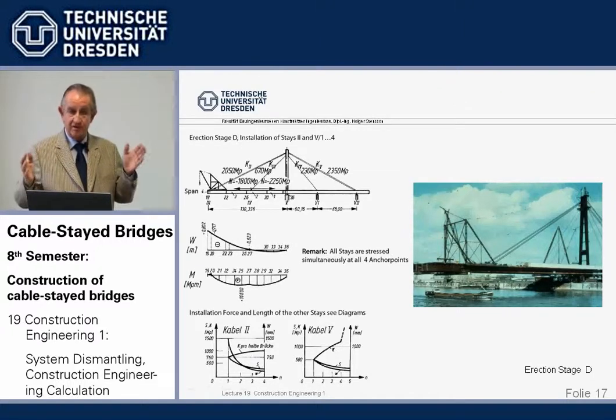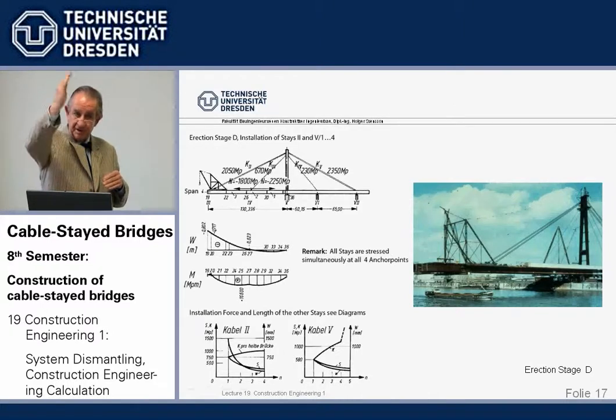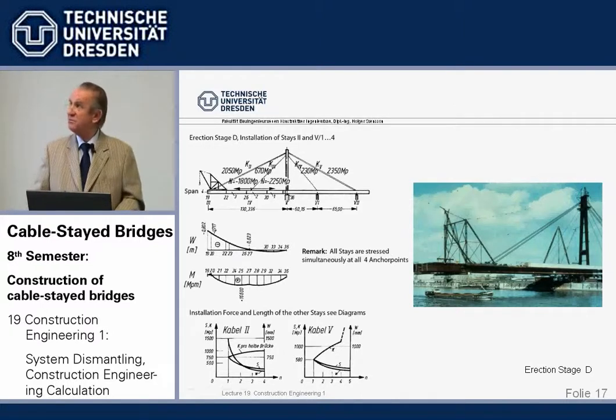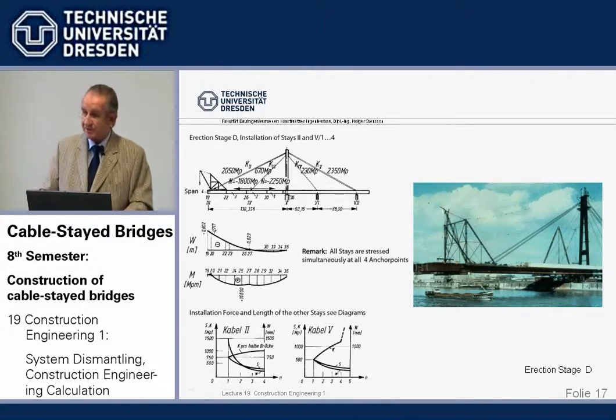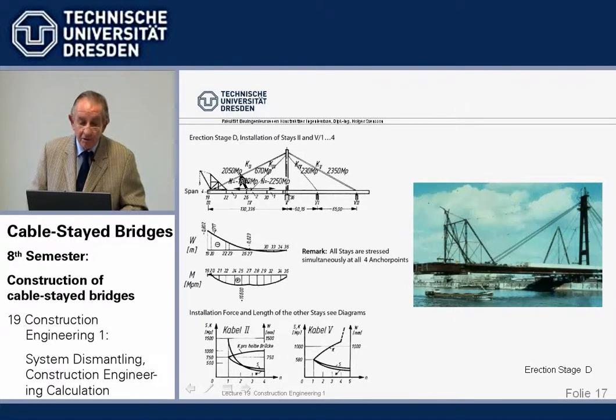So if we have large cable distances and a flexible steel beam in concrete, that will all be reduced. Then we can have this here, 2.5 meters going up and down, which is considerable. I mean, that's more than the top of the door. And it's a substantial beam. Well, we have substantial forces there. And now we know we have these cable forces in here. And we have, of course, the backstay, corresponding to this forestay. We must anchor the force back here into the pier.